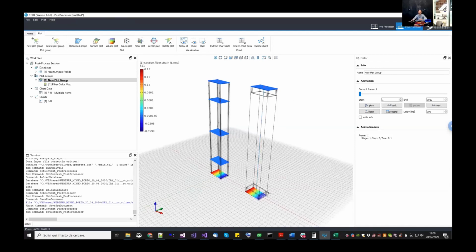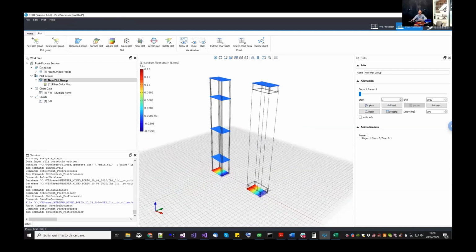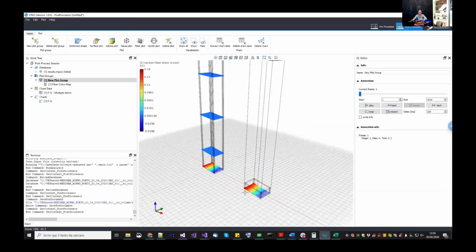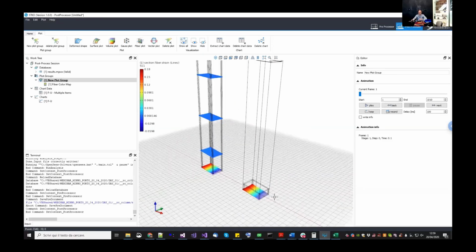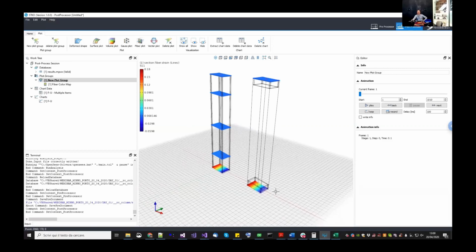Okay, so it will be very similar to this one, but without the finite length. This basically implies something, that the response that we will assign to the nonlinear zones here will not be, like in this case, a moment curvature, but it will be a moment rotation. And to show you something else, instead of using a zero length that has a fiber cross-section, we will use a zero length with a phenomenological spring, moment rotation diagram, okay?